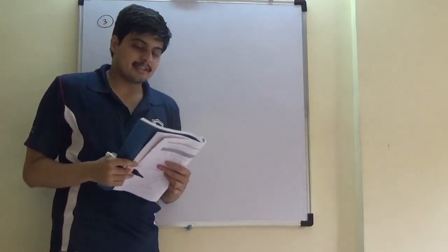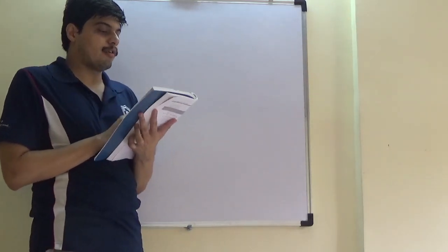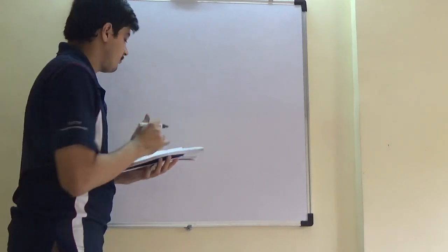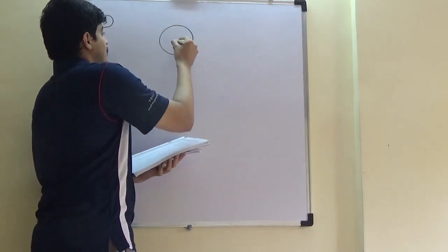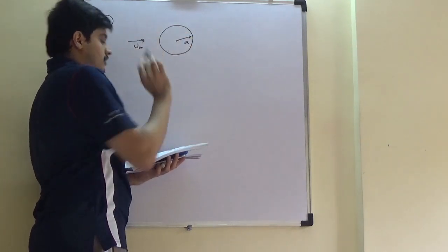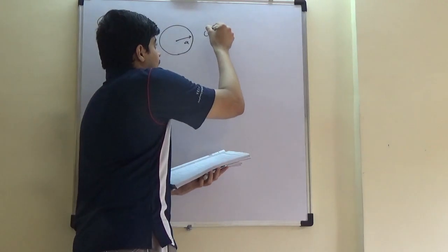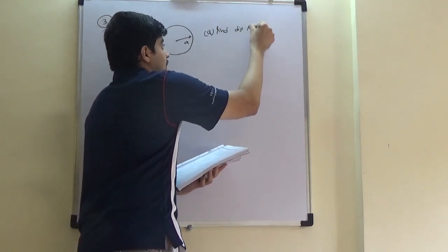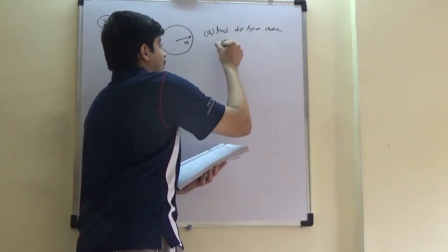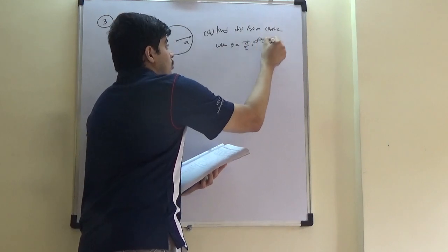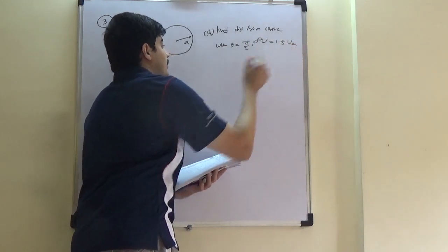On a stationary cylinder of radius a, there is a uniform velocity u infinity all over the cylinder. Stationary cylinder, radius a, u infinity. Standard problem. First, find the distance from the center when theta is pi by 2 and u is 1.5 u infinity.